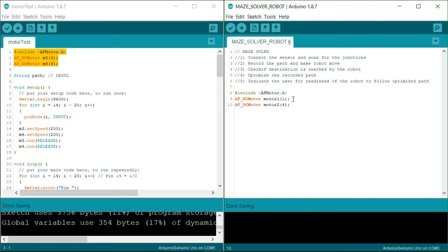So the reason number 1 why I'm using separate ICs for both the motors is for having better current stability and for better heat dissipation, so that the complete current that a single IC is actually consuming is just for a single motor, so that ICs won't heat up. That's reason number 1. And reason number 2 is for some reason I'm not having a proper rotation on the same IC.